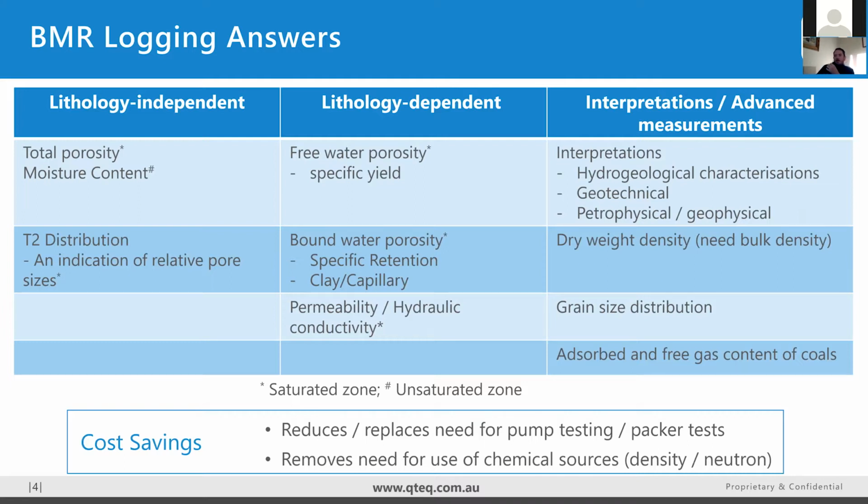All of this is great as a single tool measurement, but the real power of any geophysical measurement comes from combining all of our other data streams. If we have density or resistivity measurements, we can start doing things like a salinity analysis of your aquifer, or calculate a dry weight density or dry bulk density. These are all important inputs to your resource model, depending on what that resource model is.